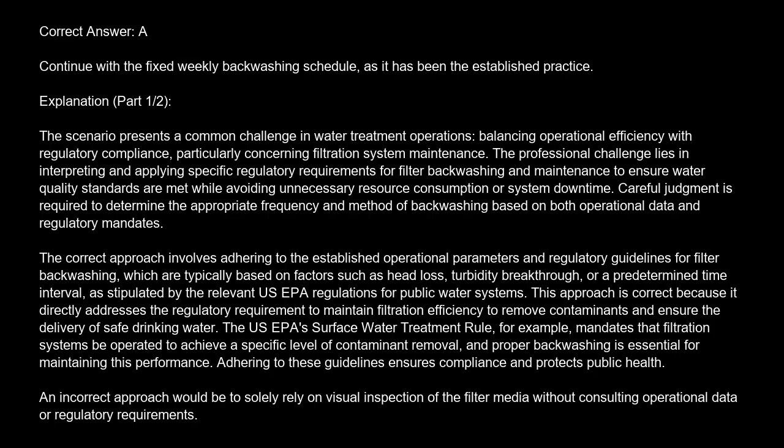Careful judgment is required to determine the appropriate frequency and method of backwashing based on both operational data and regulatory mandates. The correct approach involves adhering to the established operational parameters and regulatory guidelines for filter backwashing, which are typically based on factors such as head loss, turbidity breakthrough, or a predetermined time interval, as stipulated by the relevant U.S. EPA regulations for public water systems.